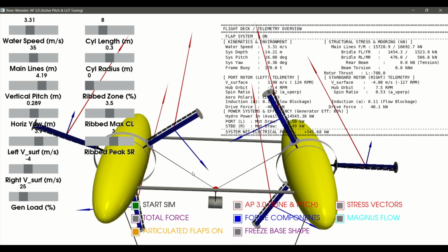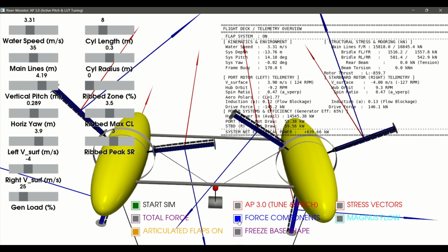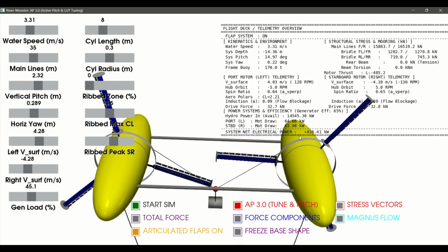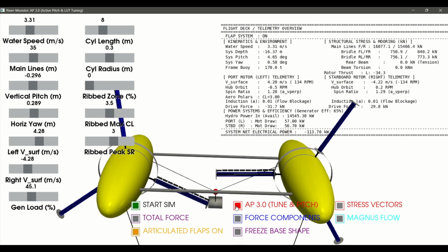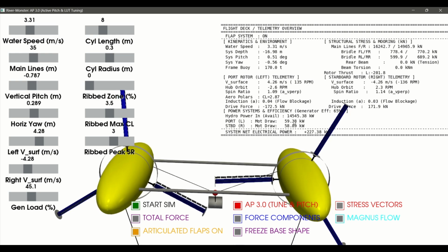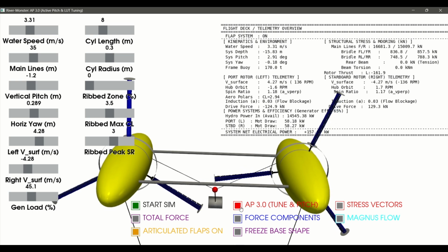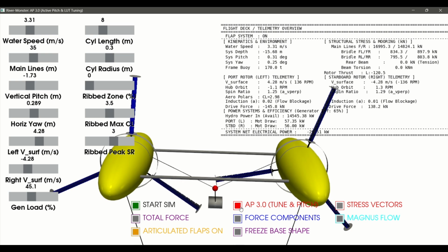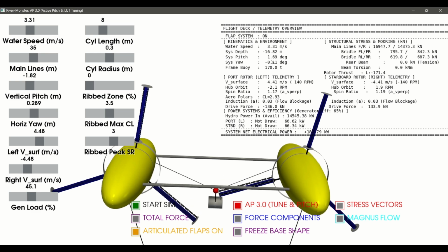Of course, the ocean is a highly dynamic environment where manual tuning is insufficient. We engage the autopilot. Watch the control sliders on the left as they begin to adjust autonomously. Our control algorithm continuously calculates the parasitic power drawn by the spin motors against the gross power yielded by the generator. It relentlessly hunts for the absolute maximum power point, while simultaneously monitoring the structural pitch and actively trimming the winches to keep the platform perfectly level.